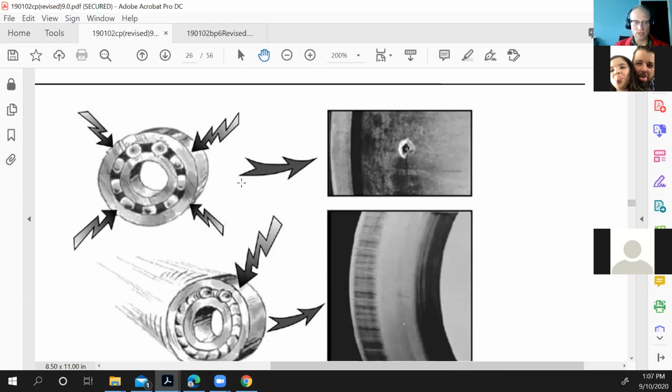Now you can get that from working on tracks. Yeah, if you put your ground somewhere while you're putting the grousers on tracks, welding those back on, if you put your ground in a place that's maybe a bit far away, so that you don't have to move it every time you roll the track over, that might cause that, absolutely, yeah.